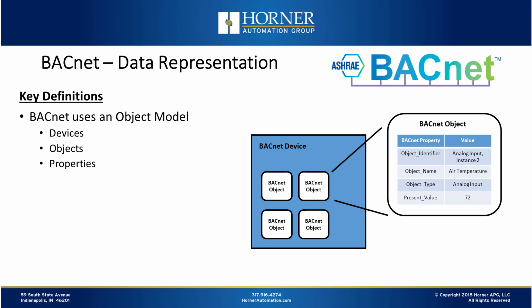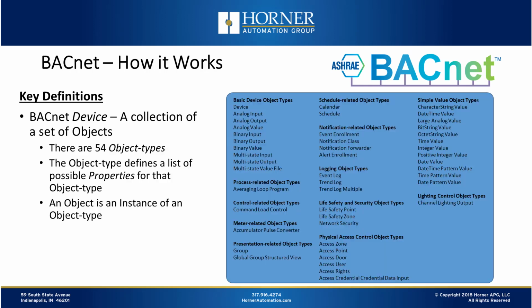All right, so now let's start talking, just like we talked about with Modbus and with Ethernet IP, about the model for the network and how data is represented. We're going to do the same today with BACnet. So like Ethernet IP and the CIP protocols that we talked about a few weeks ago, BACnet does use an object model. Okay, so it's based around devices that have objects and those objects that have properties. So let's dive in. Let's start with BACnet devices.